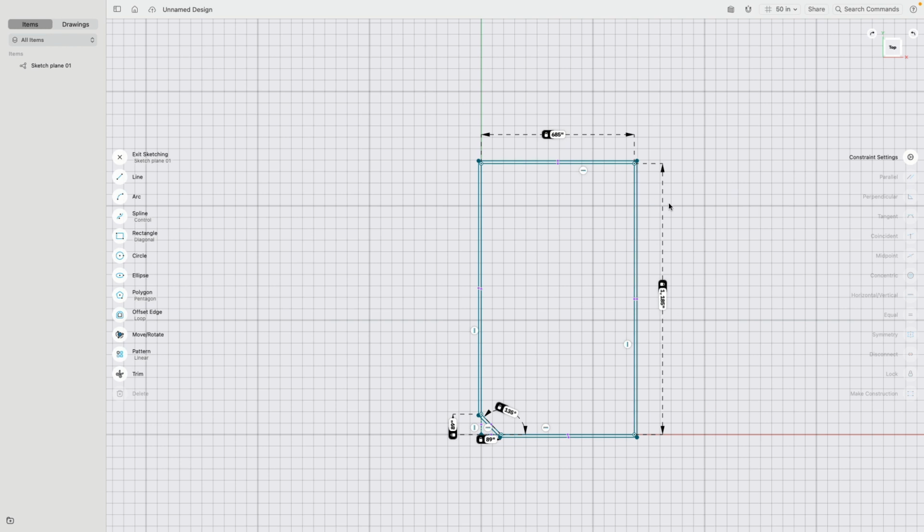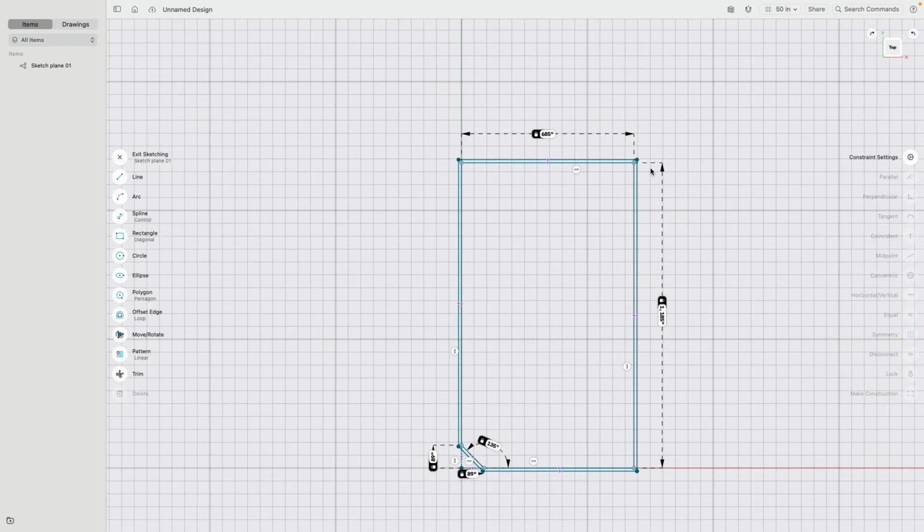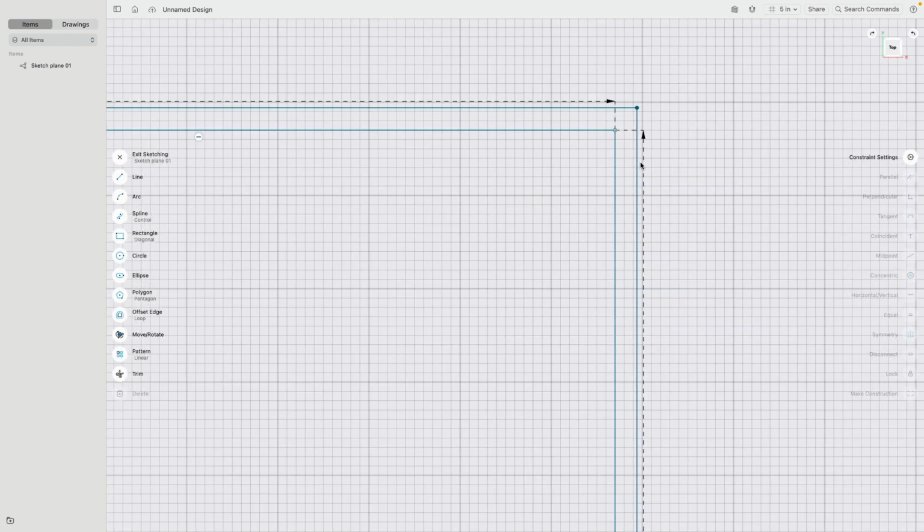We can now go ahead to also add a little bit more of interior elements and then the doors. Maybe let's start up here. And we'll go to the line command, click a line there, right click, click a line there, right click. Okay, very good. And right click one more time or escape.